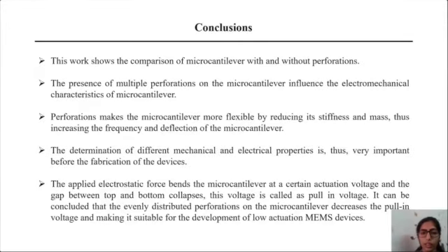Here in conclusions, this work shows the comparison of microcantilevers with and without perforations, and the presence of multiple perforations influences the electromechanical characteristics. Perforation makes the cantilever more flexible, reducing the stiffness and the mass, therefore influencing the frequency and deflection. Therefore, it can be concluded that evenly distributed perforations on a microcantilever decrease the pull-in voltage, making it suitable for the development of low actuation MEMS devices.